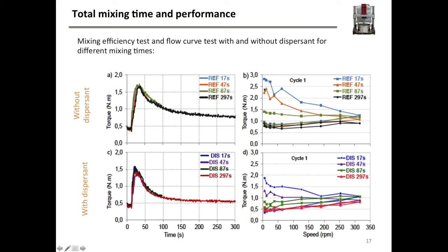So if this was concrete that was in my famed screw conveyor that I mentioned a few times already, where you would mix at the same time you convey, this would not give you a very good result. You would get concrete that is likely segregated and of poor quality at the end of your conveyor. Of course, we see what we also expect from the other curve. The 47-second mixing, the orange curve, is hardly better, the green barely gets there, and at 297-second mixing, we get a concrete mixture that's quite decent.